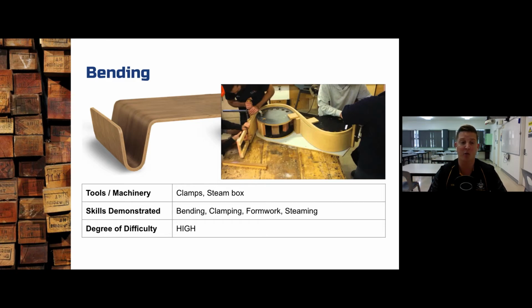In Sydney, when we talk about the appropriate amount of moisture to leave in, we normally talk around about that 15% mark. So you may hear this term equilibrium moisture content, or EMC, and for Sydney we're really looking around that 15% mark. What that actually means in real terms is we have moisture in the air in Sydney. So it's not a really dry environment, but it's not a really steamy environment. If we think tropical rainforest where it's really steamy and really damp, that would be a much higher moisture content in the air. And if we were thinking maybe in some of the desert environments where it's really dry, we might have a lower moisture content in the air.